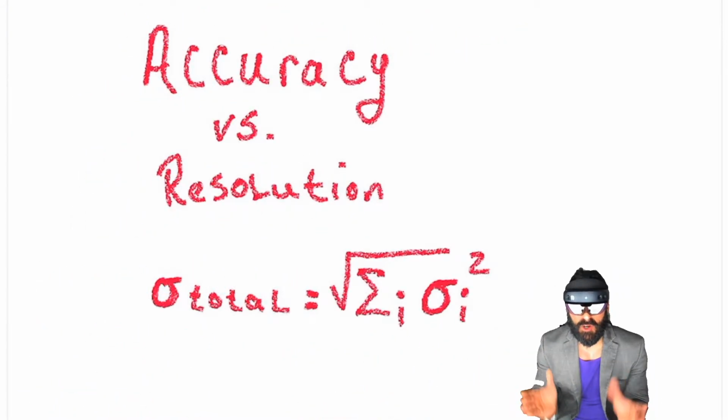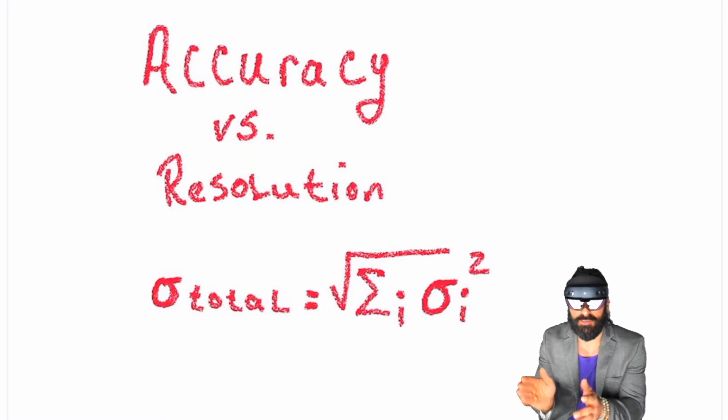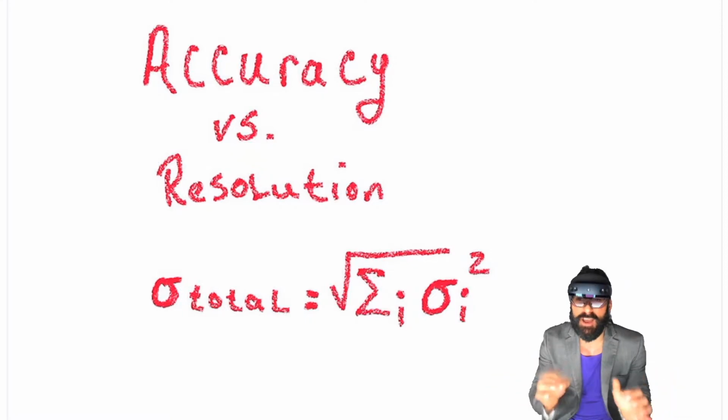Analog to digital converter, accuracy versus resolution. Now every single ADC measurement will contain a plethora of unavoidable independent errors that influence its accuracy. Now where you see OI, this is going to represent every single independent error in the circuit. Now the total error deviation rate can be shown as this equation, which is including the variety of errors such as sensor anomalies, amplifier gain, ADC quantization, resolution error, offset, and noise.